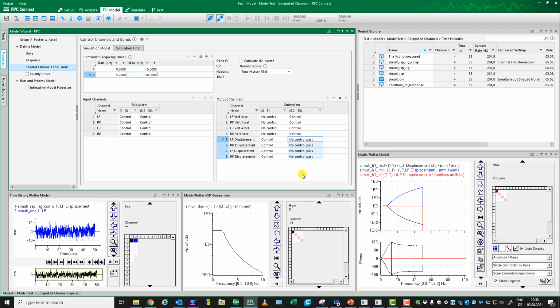So in this case, it looks similar to the correlation option we had in RPC Pro, but please make sure the way the software is designed, we only want to have the channels which do contribute or might contribute to a drive change, the candidates for control channels, only put into your FRF. This gives you the flexibility. If you know that this channel might contribute to a drive change, or you will use it in future to change your drives, that makes it flexible to use this FRF on your needs.